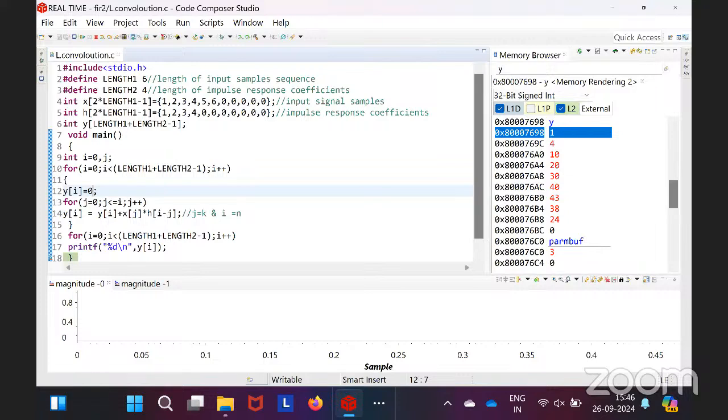Word lengths come into the picture when you are using the hardware, doing it in FPGA or any such thing. Python and MATLAB take defaults, you need not declare them. Whatever value you give, it will take default float, or even a long also, long 32 will be 64-bit. Float or double you can work on. So when you are using hardware, these restrictions will come into picture. Then you can declare them there and check it.